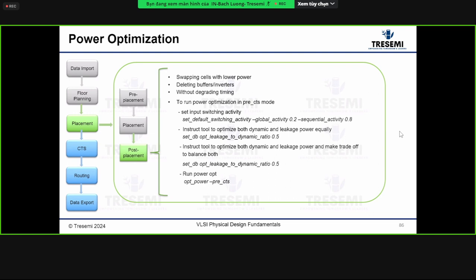So I give it a 0.7. I think that's what it is. So you can check the man page on this, and you give leakage more weight if you do a handheld application chip. Or if you do a plug-in, very high speed chip, then you give dynamic more weight. So I just want to add those kind of things.